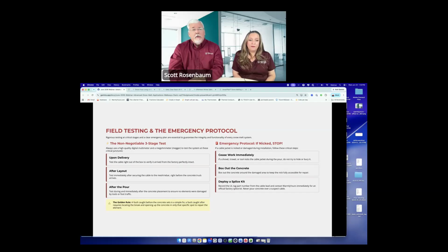So a couple more things on this. Upon delivery, test the product, because what we run into a lot of times is they'll get big boxes of all this stuff, then the concrete people will be there ready to do the install, and they test it for the first time and something happened to it between us and them. That's why you need to test it the day you get it, because then we can say, hey, this one roll tests bad. I've got a pour coming up in 2 weeks. Okay, perfect time, we'll get you the replacement. And now you're not up against it.